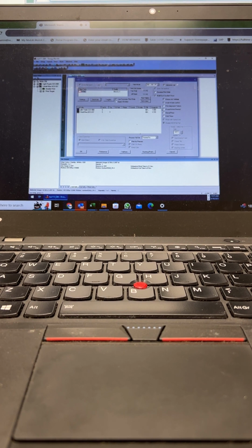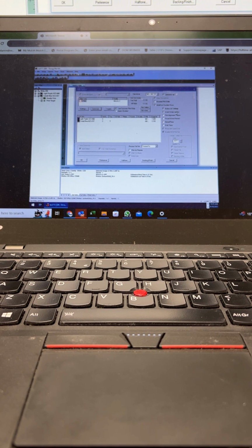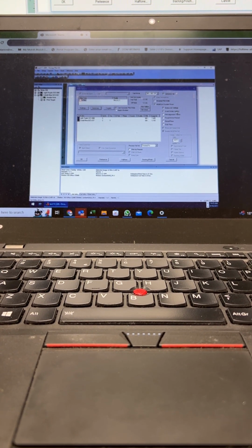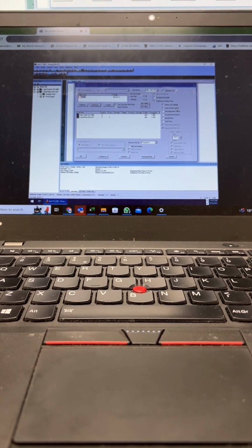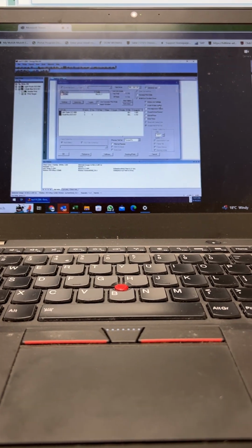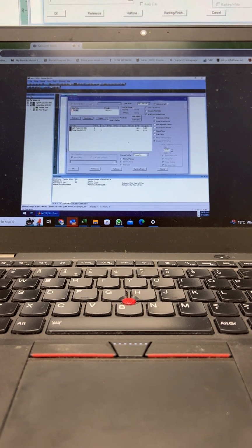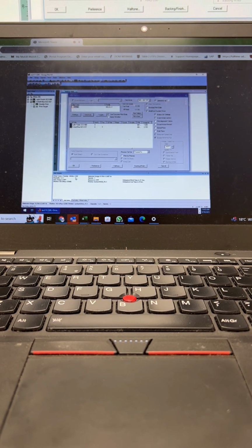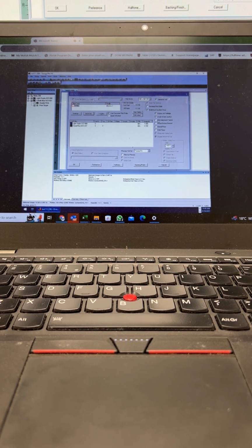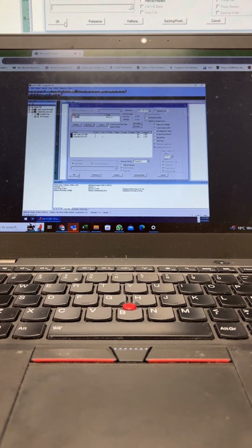There are a couple other things that can help with output and troubleshooting, and that's the output job settings and invert warm-up bar. I recommend turning these on by default, and I believe in Omega 8 they are on by default. This will print a physical black bar or a colored bar at the beginning of the job that has all the information about the file, what the vinyl is, what the software version was, how many repeats were in the job, things like that. That makes it much easier to work with the file and know what's actually going on. So that's the print options screen.